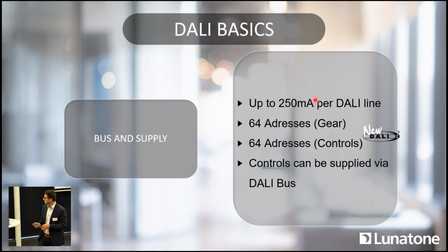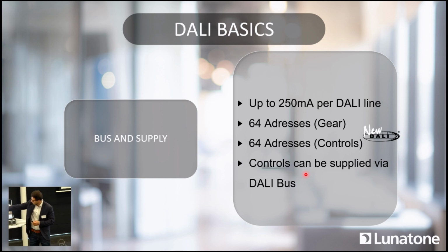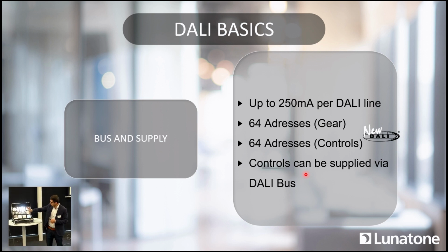I have something prepared. And controls, also maybe a nice thing to know. Controls, so those devices, if they are not too power consuming, then you can supply them via the DALI line. So those devices don't need mains power. They are powered by the DALI line.